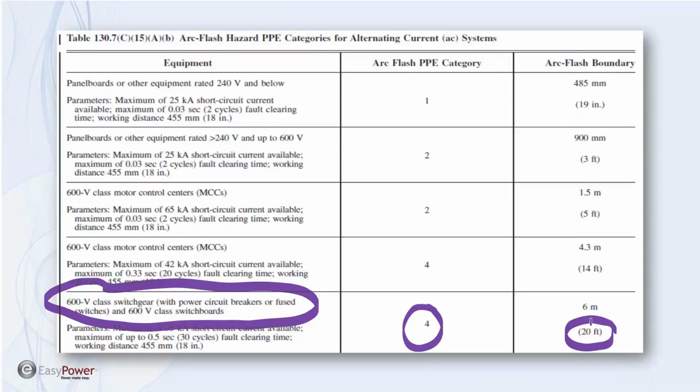The other thing is, if you talk to electricians out there, I'm going to say that probably 90% of them will not look at this data. They'll not examine that. They will see I'm downstream on a VFD, and so it's 30 cycles, or it's that high, and then what's your clearing time, or what's your available fault current, and they don't know.